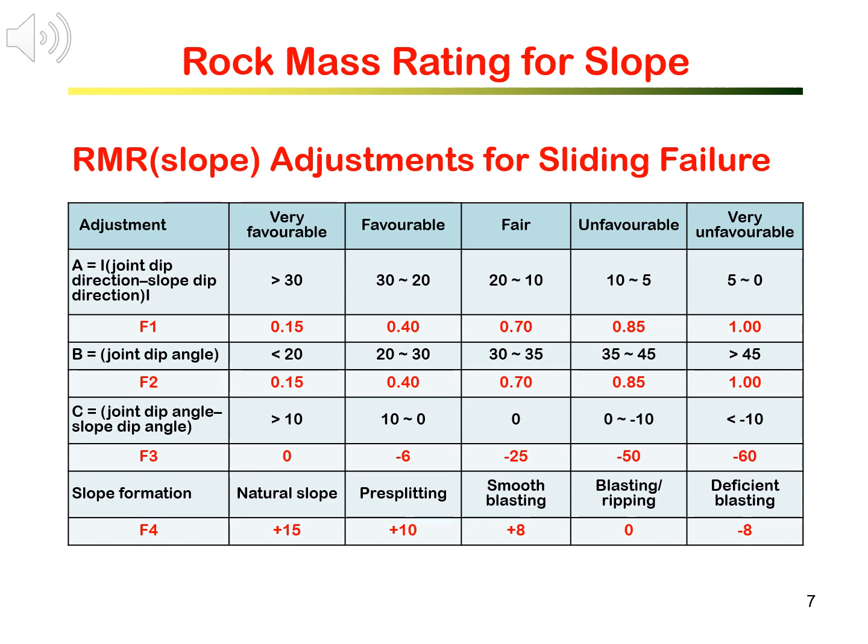F4 is reflecting the condition of the slope, particularly to account for badly excavated slope surface, for example, bad blasting practice. Here, standard blasting is considered as normal and has no adjustment. Positive adjustment is given to high quality blasting practice, while negative adjustment is given to bad blasting practice.